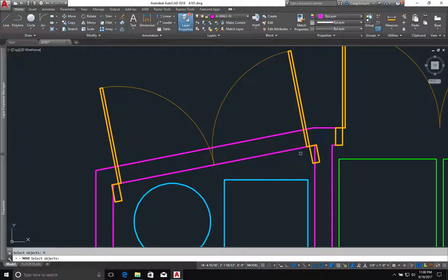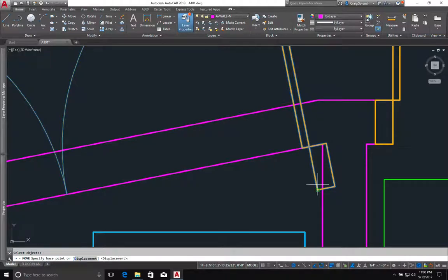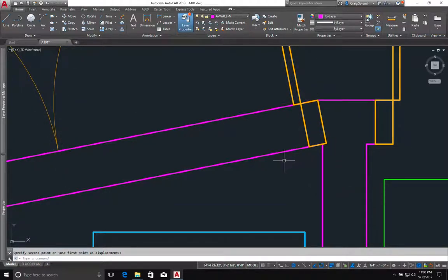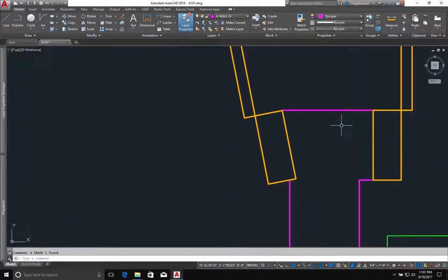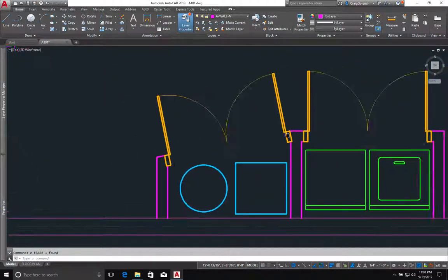Okay, here at the move command, the last thing I did is I rotated those objects. And when I go to move them and I type pre for previous, it'll automatically select those objects. And so now I can zoom in, move it from there to there. Basically means I can delete that inside line and then BR on the outside line and pull it all the way back to there. And that little piece I can delete. It's not perfect, but it'll do.